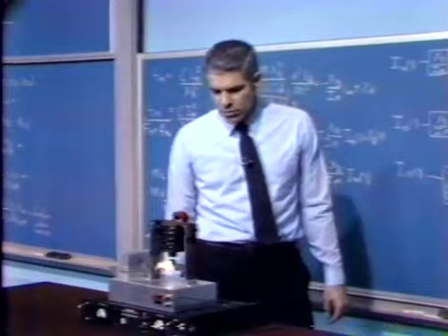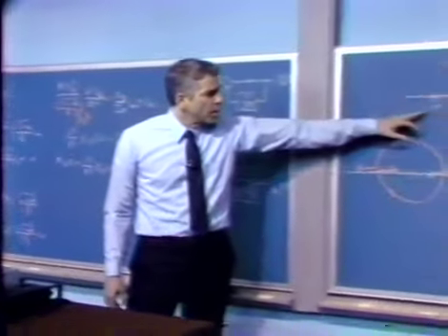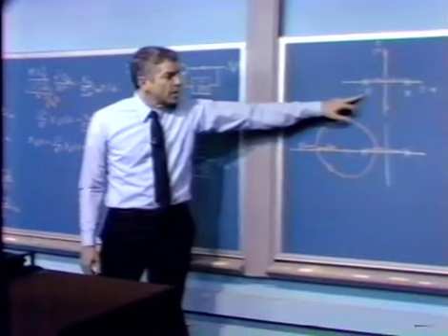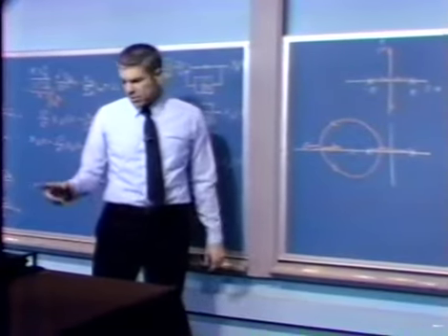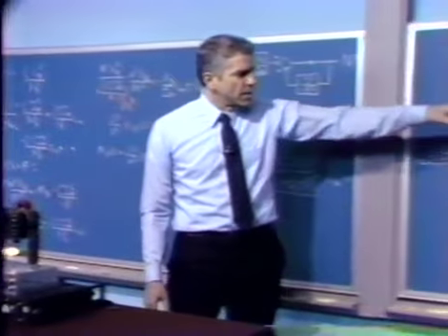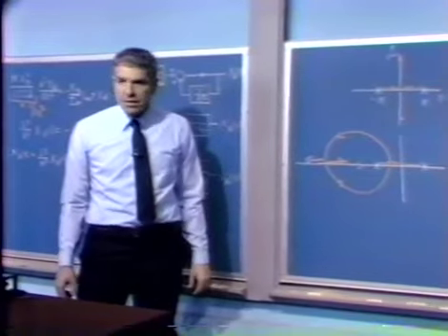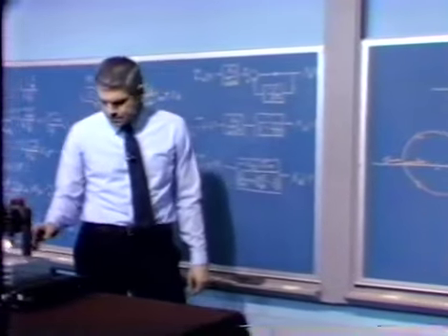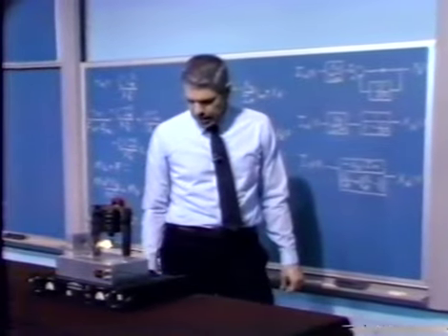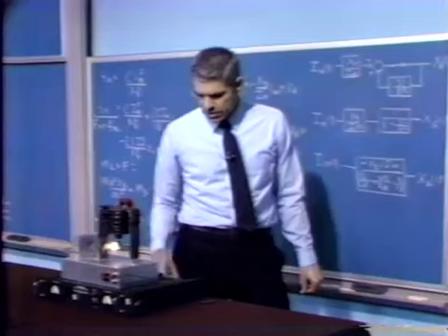To this day, I don't know the exact value of K, for example. I suspect it's somewhere on the order of 20 radians per second for this particular system, but I've never gone through that. I estimate that from really the location that the zero ended up with and the amount of A naught that I needed in order to stabilize things. So my guess is that the value K is somewhere in the order of 20 inverse seconds for this particular system.